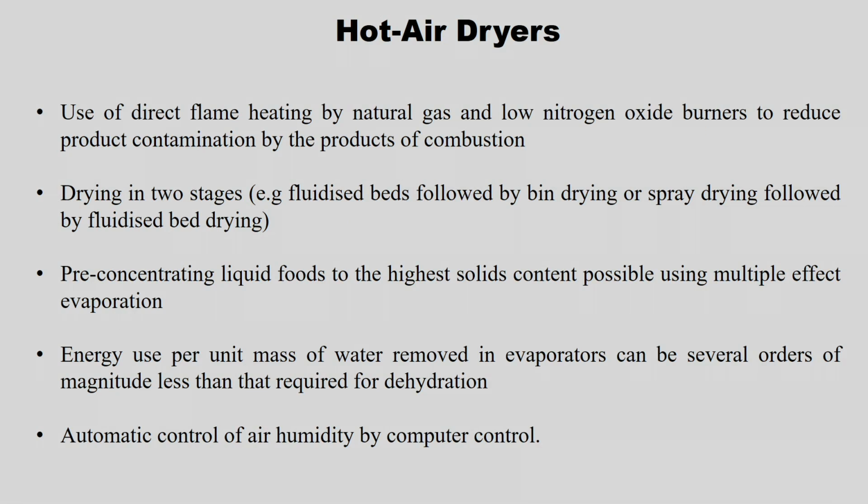And use of direct flame heating with natural gas or low nitrogen oxide burners to reduce product contamination by the products of combustion, right. So, if we use direct flame or low nitrogen oxide burners, then product contamination can be taken care of. And drying in two stages.